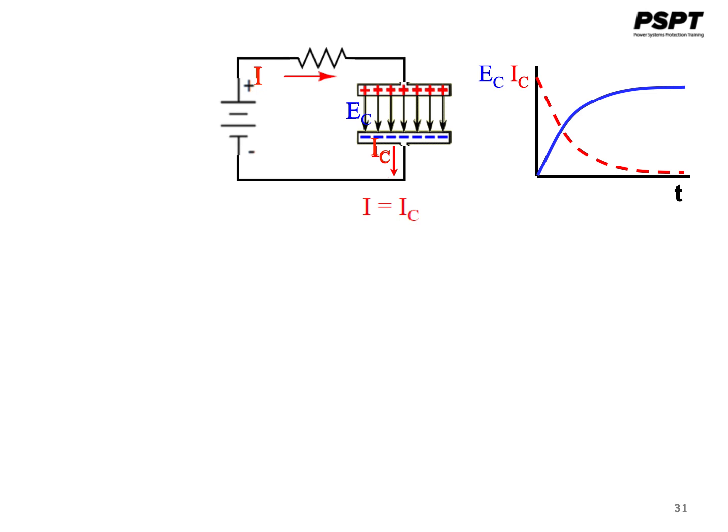So what you've seen here is that the current will be instantaneous when you close the switch. So it'll be at the full value, only limited by the resistor, which is limited by Ohm's law. Bottom line here is you're going to have instantaneous current flowing, and the voltage drop across the capacitor is going to be 0 and slowly building up. So the current will lead the voltage in this case.